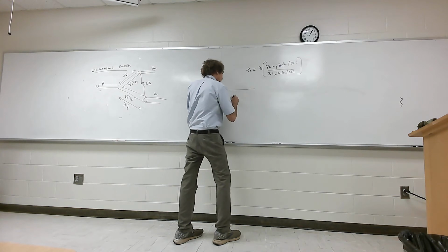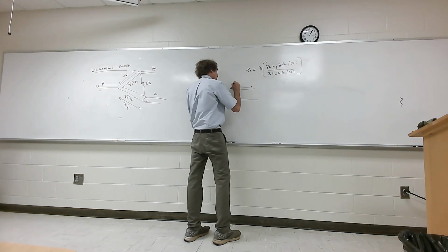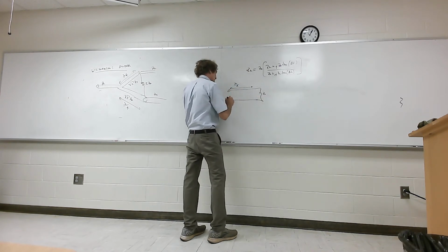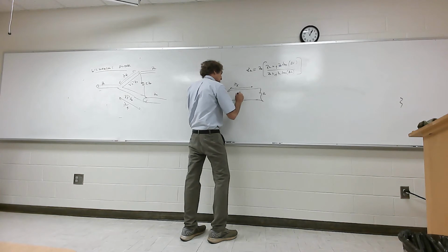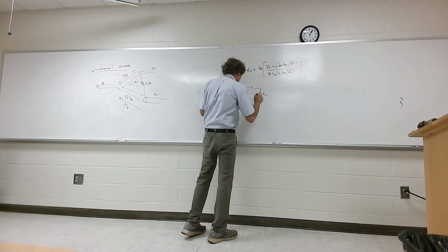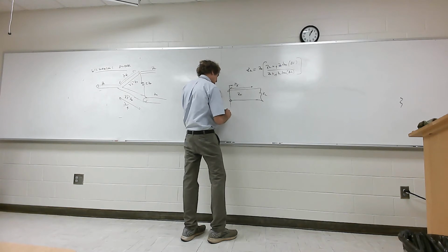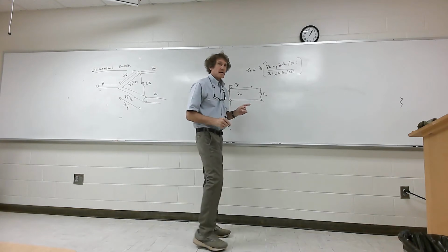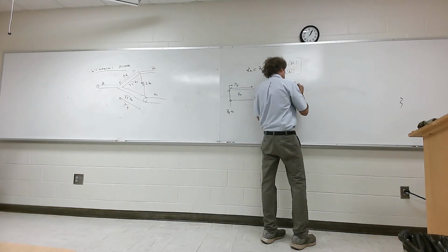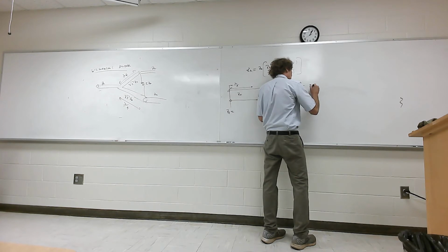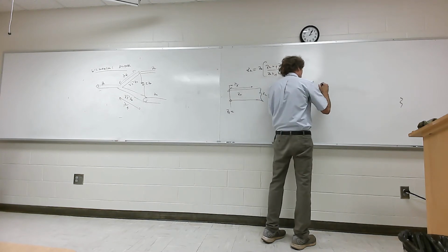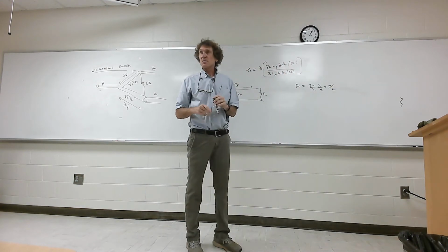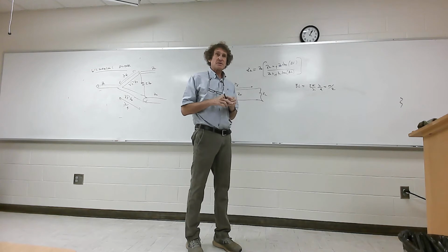So if we had something that was a quarter wavelength long, and this was Z naught right here, what would the impedance here be? Or I'm sorry, that's Z naught, and this is Z load. Well, when you look at that, what would Zin be? Take a look. If it's a quarter wavelength long, the key thing is looking at this argument of beta L. Beta is 2 pi over lambda, and if the length is a quarter wavelength, beta L is pi over 2, right? Please just watch this. Do y'all follow me? What's the tangent of pi over 2? What's the tangent of 90 degrees?